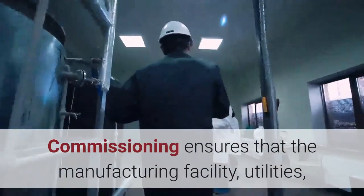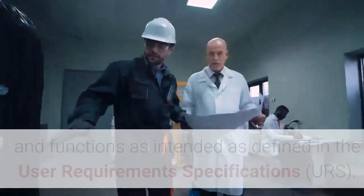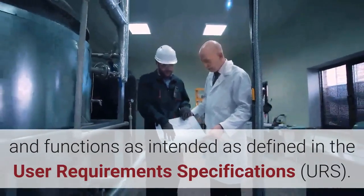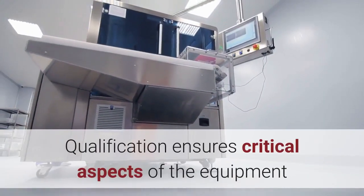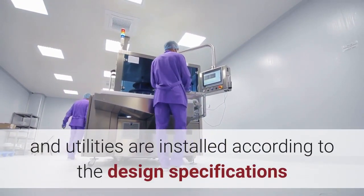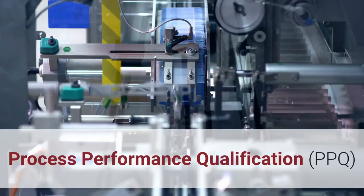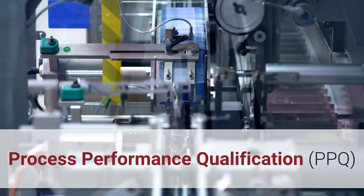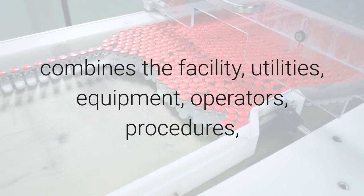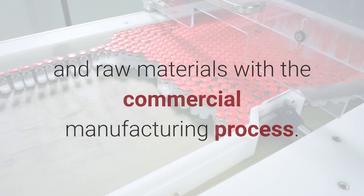Commissioning ensures that the manufacturing facility, utilities, and equipment is designed properly and functions as intended as defined in the User Requirements Specifications, URS. Qualification ensures critical aspects of the equipment and utilities are installed according to the design specifications and suitable for their intended use. Process Performance Qualification, PPQ, combines the facility, utilities, equipment, operators, procedures, and raw materials with the commercial manufacturing process.